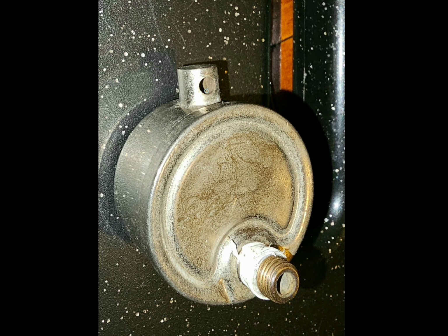Now on the Gordons, on the other hand, when you look at the outlet, it's damn near identical to the inlet. So yeah, if you actually put your lips around this and blow on this as hard as you can, you probably don't even have to blow as hard as you can, the thermostatic contraption that's in here will get stuck in a closed position. And this is where it really gets interesting and why I say you have to pay attention to these air vents and know their personalities. This is why you need to know where you should install these things and where you should not install these things.